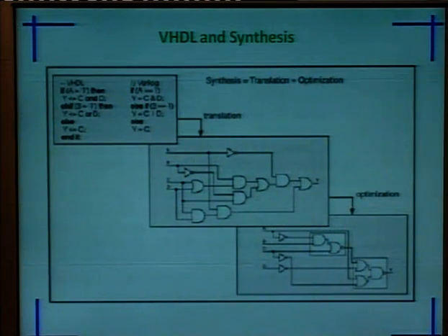In structural modeling the processing is parallel, so speed is very high, but due to the large number of components, signals, and port mapping, power consumption will be high. So there is a trade-off between speed and power, which applies to behavioral and structural modeling. Before going to the synthesis process, we first have to check which type of modeling will be suitable for our design. Once our design is ready with the specified modeling, we will transform it to the gate level, and then go for optimization.